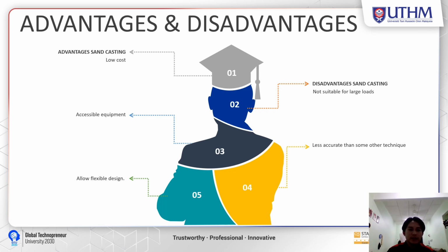The primary advantage of sand casting is cost effectiveness. The molds are relatively inexpensive to make and require little to no machining once completed. Sand casting is therefore perfect for do-it-yourself home production because the equipment is accessible. Additionally, sand casting allows for more design flexibility than other casting techniques. The mold can be easily modified to produce complex forms and details.